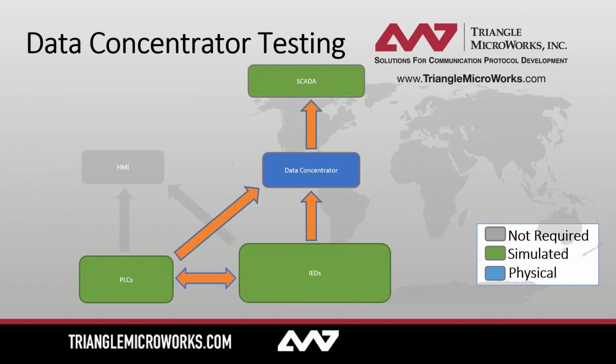We can also test a data concentrator or a gateway. You can do this by simulating the same IEDs and PLCs in the downstream data, but also simulating the SCADA upstream that the data concentrator reports to. In this situation, since DTM is able to simulate both sides of the data concentrator, we're able to automatically change data downstream and verify the proper data is changed upstream. This allows us to do an automated test of the entire data concentrator.